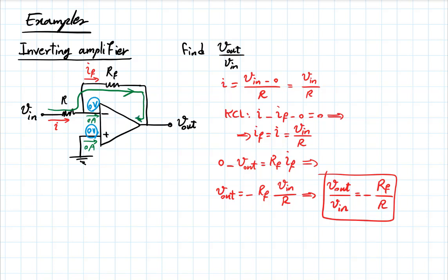Now, if you look at the op-amp, what I have inside this box, there is zero current going in from the left side and zero current, and then there is some finite current going in from the right-hand side. So what happened? Am I violating KCL? Is the op-amp getting charged up? Is it building up charge over time? Had better not do that, right? So where does this current go?